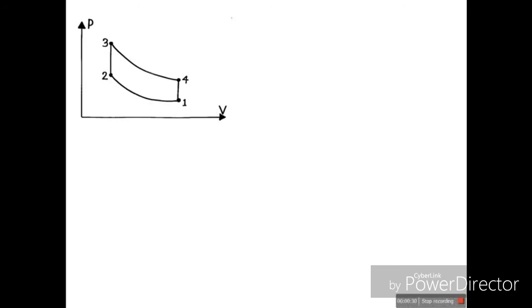For the first step in solving the problem, we need to find the temperature and pressure at point 2, which will be used later on for solving the maximum temperature and pressure. Based on the diagram Jane discussed earlier, the first process, which starts at point 1 to point 2, is described as a reversible adiabatic compression of air.